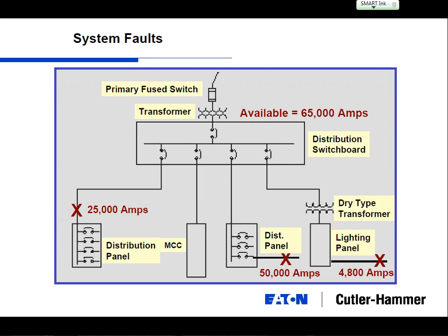When you talk about a smaller cable, maybe something this small for a 20 amp circuit, there's a little bit of copper in there, but you still have the insulation around the outside. So with a little bit of copper, the electrons are scraping the edges, I guess is the way to think about it. So there's more impedance or resistance holding that fault current from going downstream.